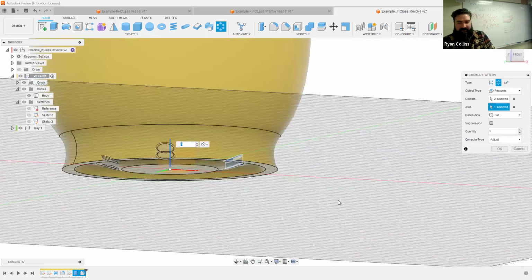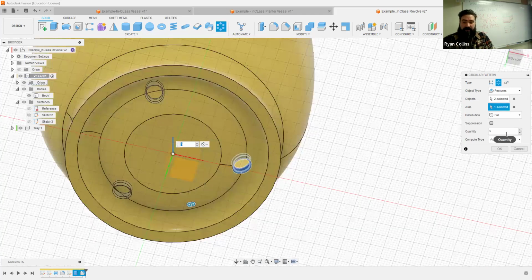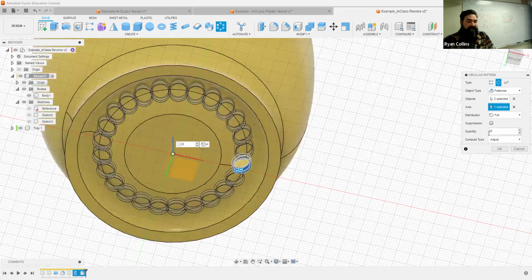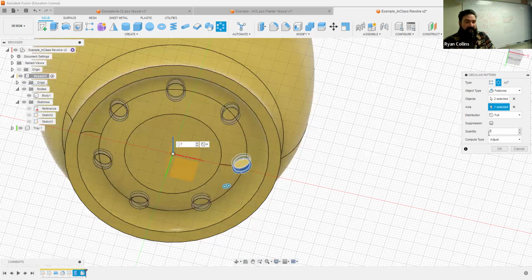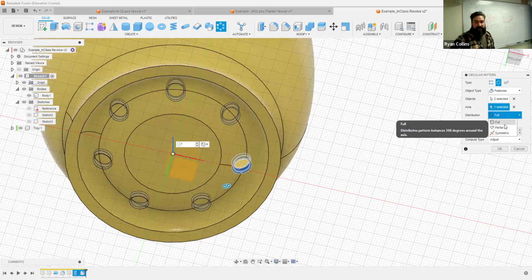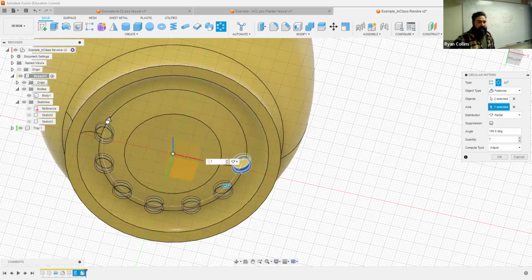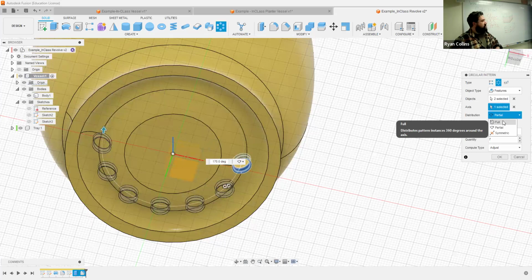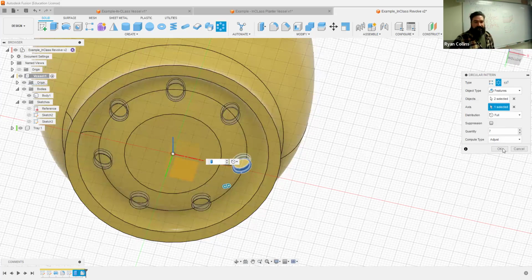It's going to create these automatically in multiples. It's automatically going to be in 3. You add however many you want. 3, 25. That's a little excessive. Maybe somewhere in between. I don't know, 7. Odd numbers always feel better. You don't have to do complete. You could, of course, do partial or symmetric, which just means you are making all of them partially around, that sort. It's up to you. But in this case, obviously, we're just going to do full, evenly distributed, all set.